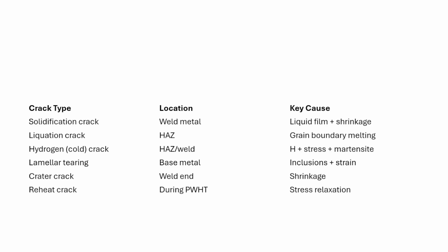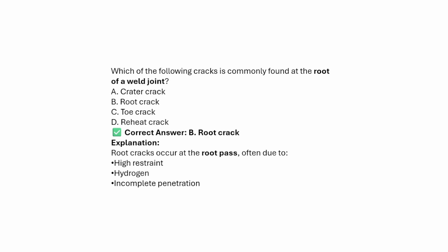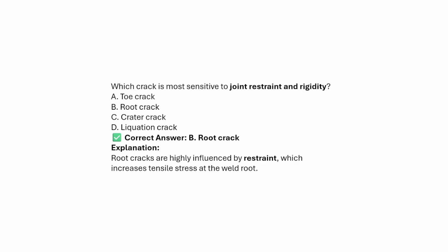And reheat cracking is during the post weld heat treatment, due to stress relaxation. Okay, next coming to the third one, that is underbead cracking and toe cracking.